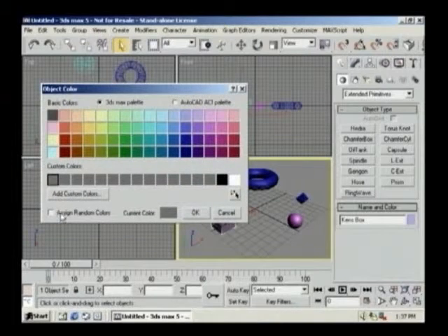With this option off, no check mark, each object will then be the color that you last chose from this dialog box. Click on a color to choose it. So if I'm creating a room and I want all the walls to be one color, I can do that. And then if I want the floor to be another color, and I want furniture or windows, so you get full control over this to help you stay organized as you build your scene.